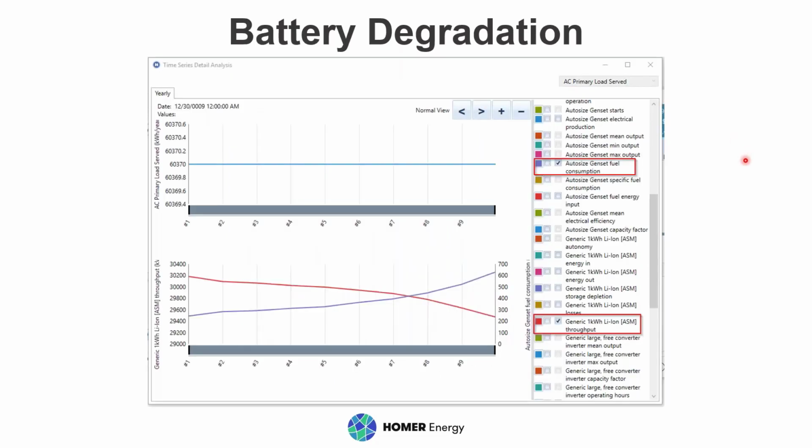Now, another important topic that I haven't mentioned is battery degradation. On the multi-year input, you can put in how quickly you think the batteries are going to degrade. On the multi-year input page, you can also show how quickly you think PV is going to degrade. The battery degradation is a lot more complicated, frankly, because it's a function of how the battery gets used, which you don't know ahead of time, and temperature is also really important for battery degradation.